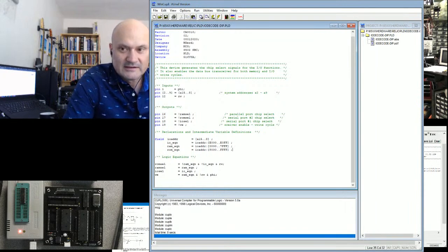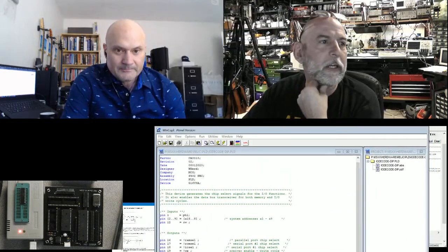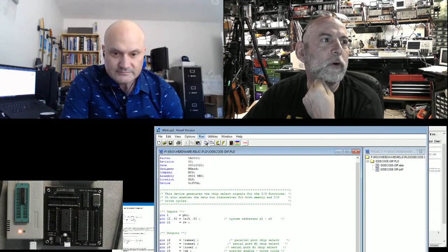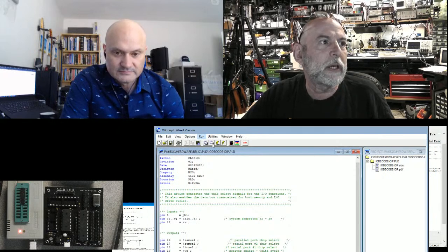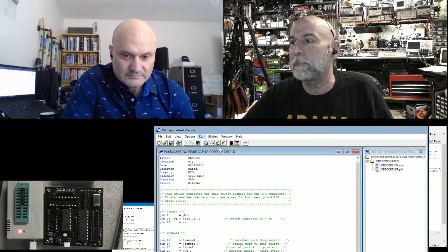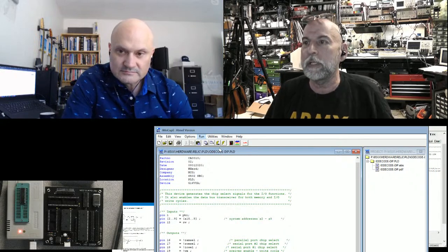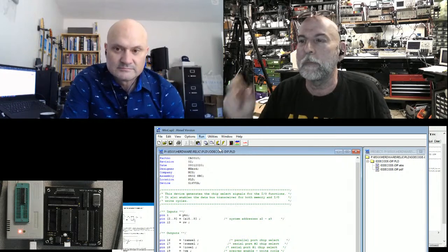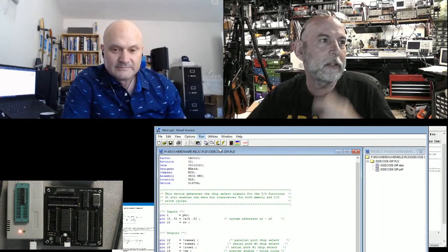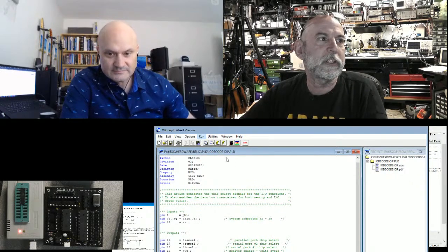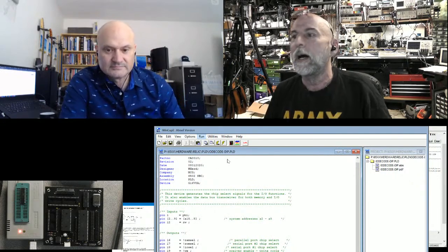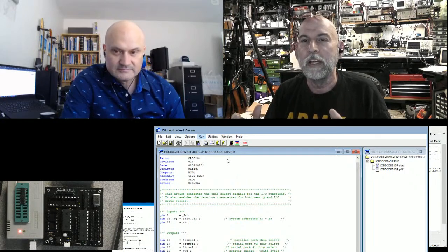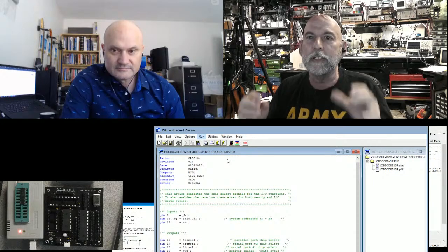Right. Yes. And I'm disappointed here. You can't see it, but when I go to run, I have 4 options. I have device-dependent compile and device-independent compile, which means I can just compile the logic to check my logic, or I can compile my logic and make sure it fits in the part I've chosen. Wow. And then the other 2 are device-dependent simulate and device-independent simulate. I'm not set up to show the simulation here, but with this simple little program from the old days, not only can you program a PLD, you can simulate it.